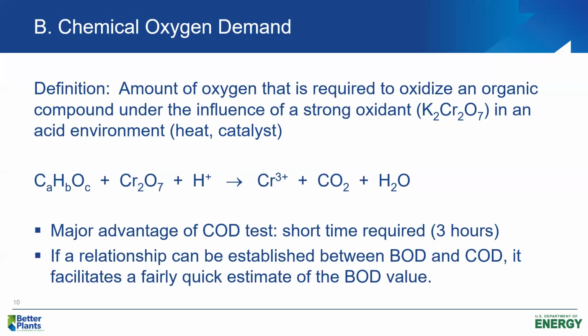So in the COD test, essentially what we're measuring is the oxygen equivalent of the biodegradable and the non-biodegradable organic content of the wastewater. So going back to what I said, BOD5 raw sewage about 200 milligrams per liter, the ultimate BOD about 300 milligrams per liter, and I usually estimate the COD of medium strength municipal wastewater at about 450 milligrams per liter.